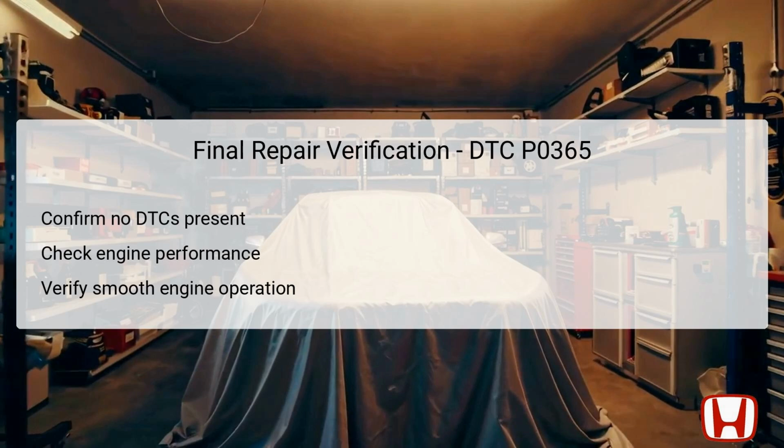Start by confirming that there are no remaining diagnostic trouble codes present in the PCM. This ensures that the root issue has been successfully addressed. Following this, monitor the engine performance closely. It should operate smoothly without any irregularities such as stalling or misfiring.